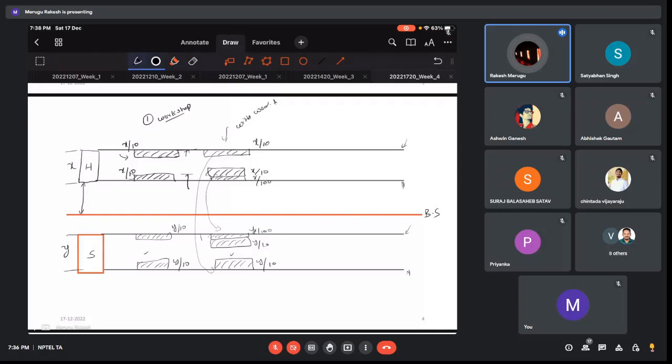So that's why there is one more system, that is the inspection gauges. In this, the philosophy is that we have kept so much time and hard work into manufacturing the product, so nothing should go to waste. So the gauge tolerance will be outside the actual tolerance of the products. Rest everything is similar.